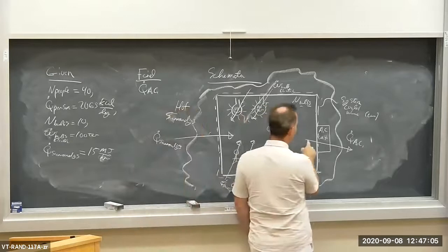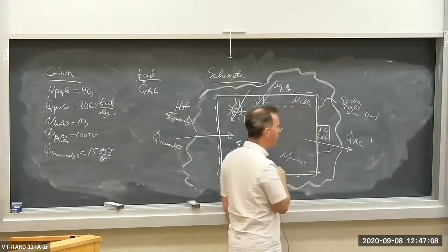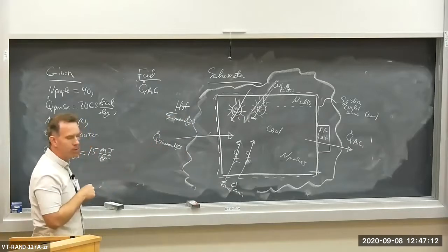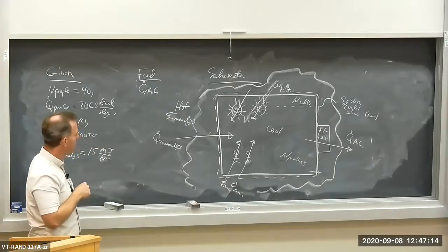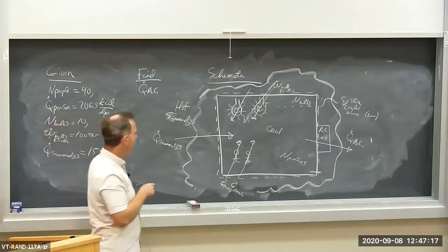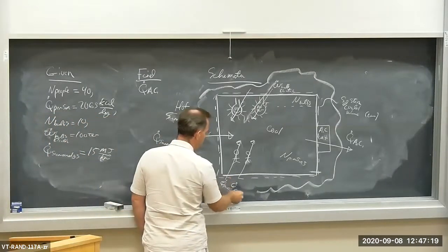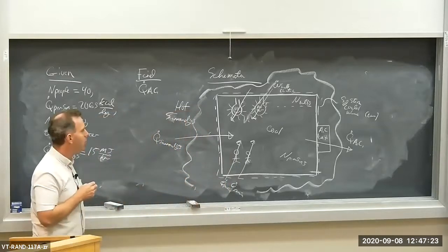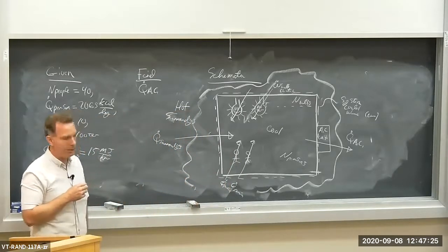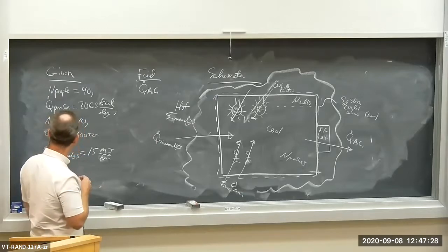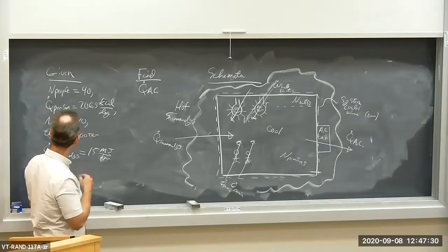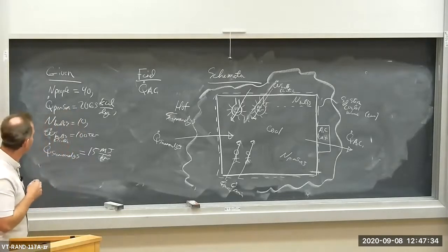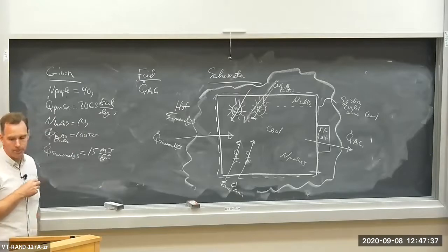We have the heat transfer out of the room to the AC unit. So that's out of the room. See the arrow indicates outflow due to the AC unit. And then we have a bunch of heat transfers to the room. And what we mean by that is the body heat being rejected by the occupants, okay? There are N people in the room, and each person is rejecting heat at a certain rate, Q dot person.